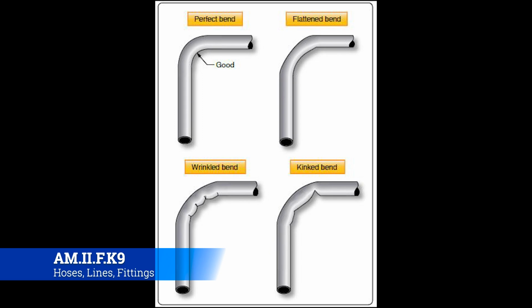The rule of thumb with the scratches on the outside of the tube, which you will see, because these things get scratched all the time in installation and just things coming and going in and out of those compartments, is that the scratch can't exceed more than 10% of the depth of the line itself. So if it's 10 millimeters thick, the scratch can only be 1 millimeter deep into the sidewall. Other than that, it's considered no good, and you have to replace the line.